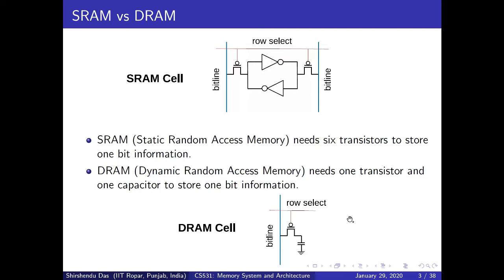That's why, as I hope you know, in case of DRAM we have to periodically refresh these cells. Otherwise, this data will be automatically discharged, because the information is stored in the form of charge, which is not the case in SRAM. So this is the advantage of SRAM, that SRAM doesn't require a periodic refresh, and this is one disadvantage of DRAM, because it requires periodic refresh.